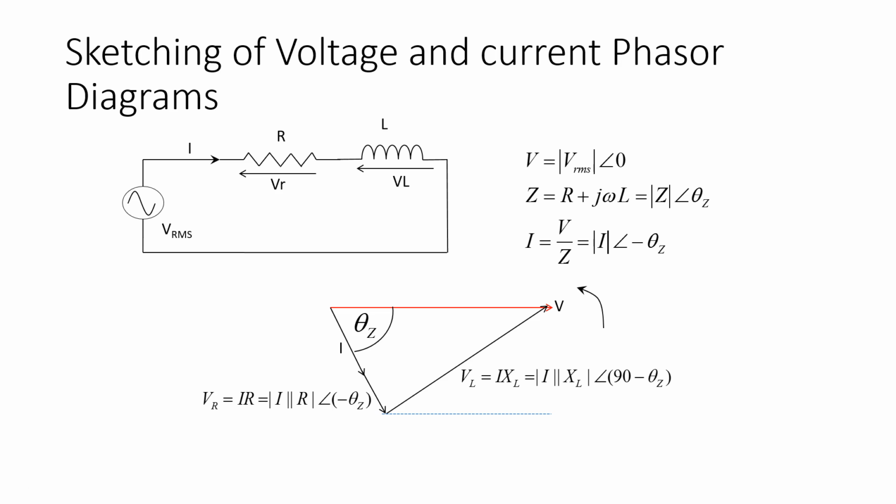One of the things that you will need to know, and that is very useful for power systems, is phasor diagrams. This is where we can graphically see the voltages and currents. So if I have this simple RL circuit, I have V, which I can represent as a phasor. This is some V cosine omega t.